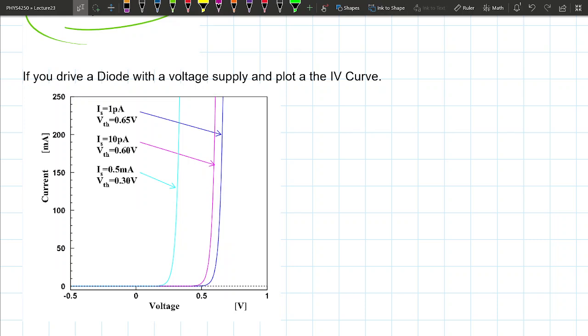And typically, there's going to be a set voltage that a diode operates at, meaning you have to overcome a certain potential in order for the current to flow, right? When you make a diode, you can make it a 0.65 volt diode, 0.6, 0.3. You can make these numbers whatever you want. There's actually a light blue line here. It's kind of hard to see. The diodes we're using are these 0.65 types. So if you apply 0 volts to it, no current will flow.